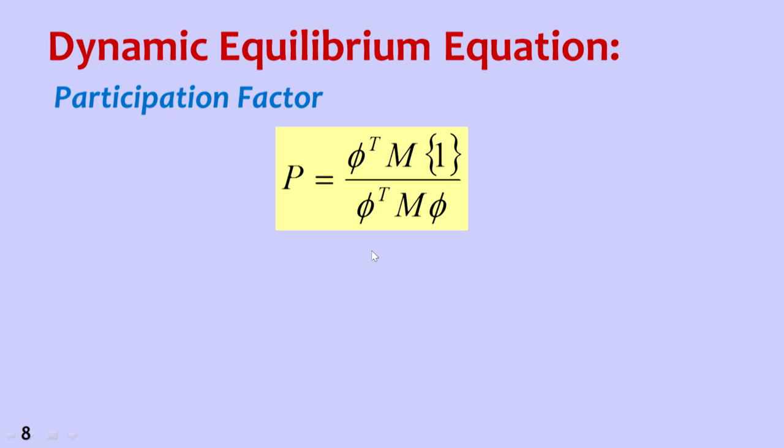So, what we do is first mode, second mode, third mode, fourth mode, we add. We add mass participation, and if it is crossing, say, 95%, then we stop at that point. So, we need not take all the mode shapes into consideration. If we take the first few mode shapes where total mass participation becomes more than 95%, we can do the analysis. So, that is what the participation factor is.